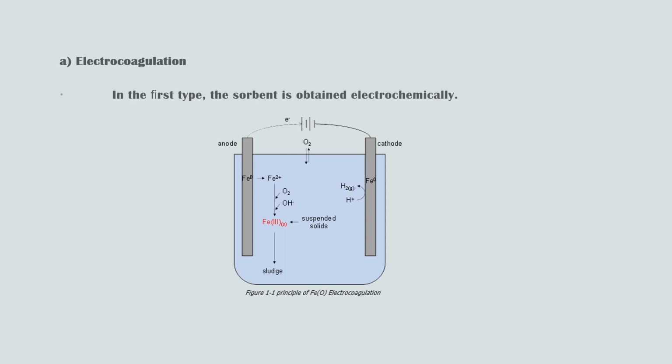The effluent containing both organic and inorganic contaminants and heavy metal salts is subjected to electrolysis with steel or aluminum anodes. During electrolysis, these anodes dissolve in the electrochemical cell, while hydrogen is evolved at the cathode. The layer next to the cathode, the water in the gap between the electrodes, becomes so alkaline that the dissolved iron or aluminum ions will form highly porous hydroxides.